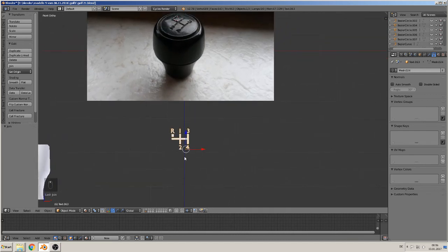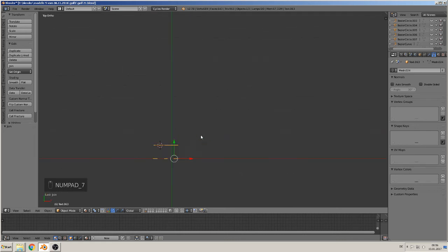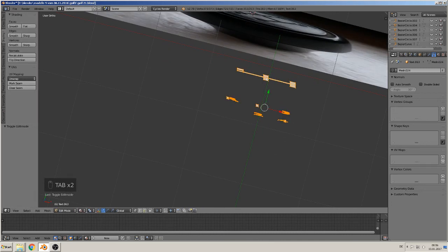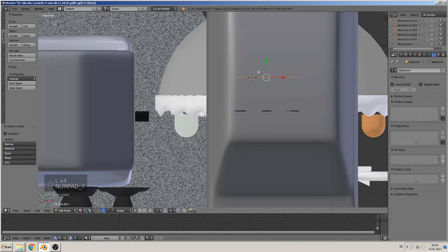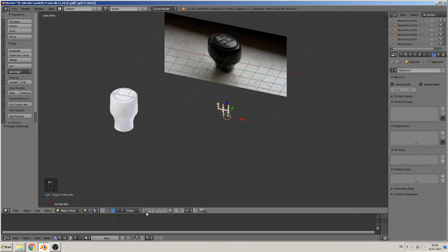Good. Now for that, we have possibilities to bring it in with a knife project or with a boolean, but I want to show another way. So we go here in Edit Mode, scale Y 0 to make them all at the same height. So we have that. Good.